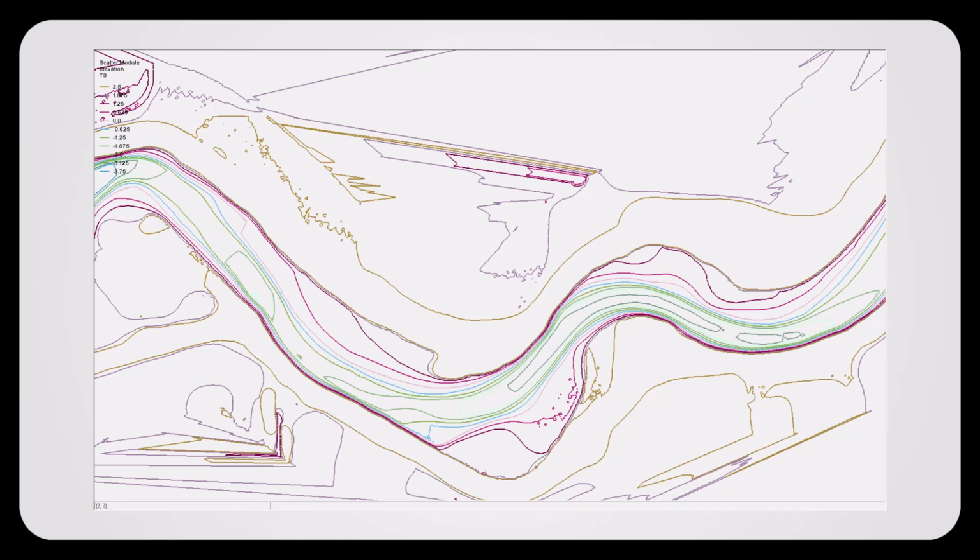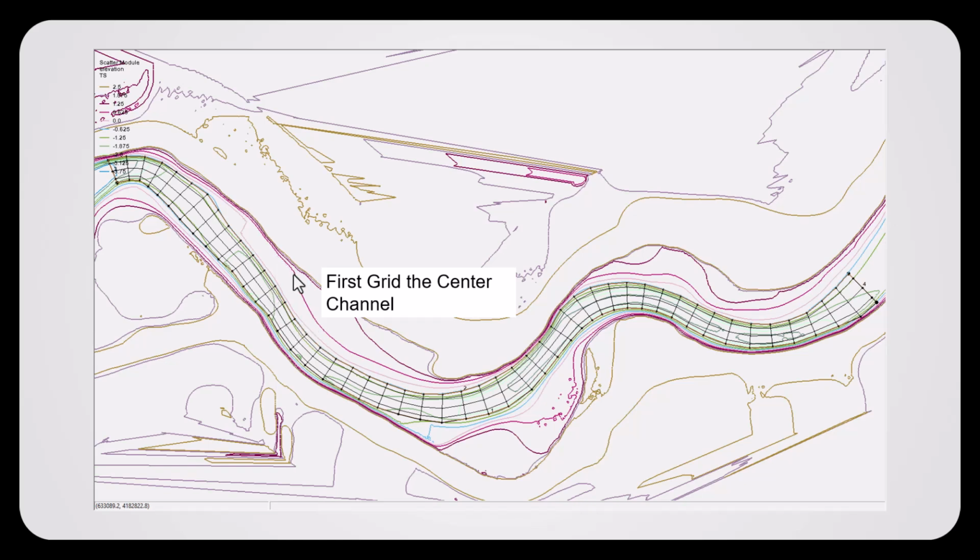The deepest part of the channel is about -4 NAVD. It's kind of in the top left up here. The lowest tides reach about 0.5 meters NAVD, and 0.45 is probably a safer or more conservative always wet elevation. Notice that the 0.55 meter contour undulates on both sides of the grid. So that is this one here, the sort of purple line, and it doesn't track the center channel very well. The center channel here is very clean.